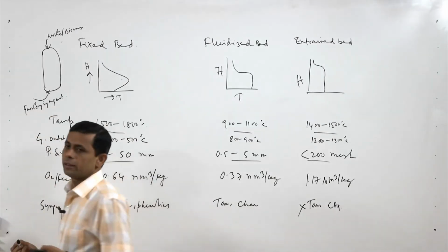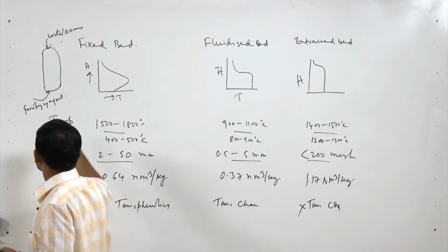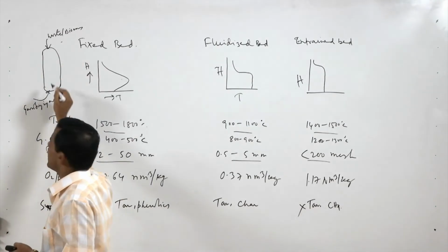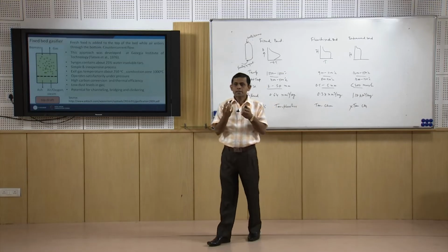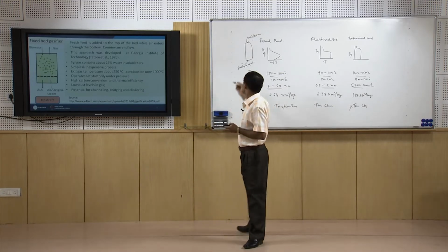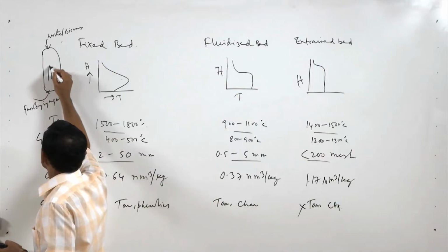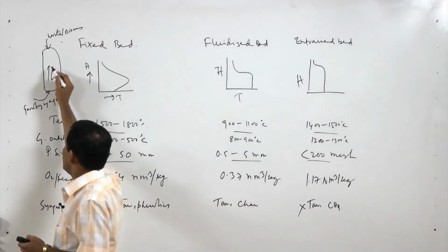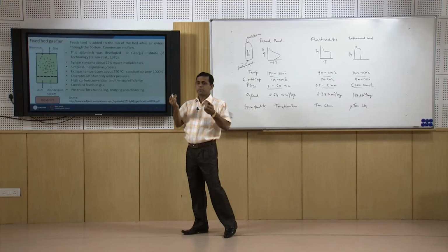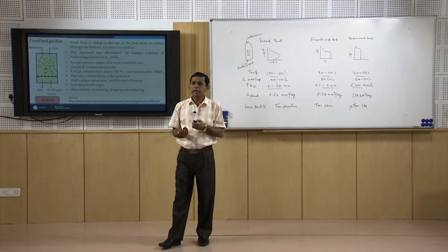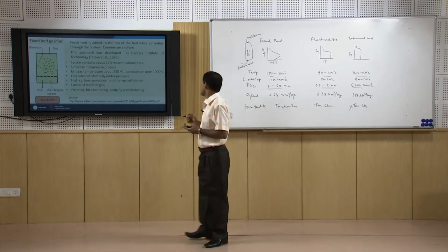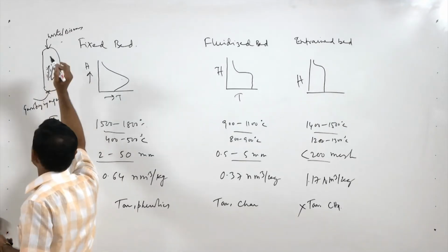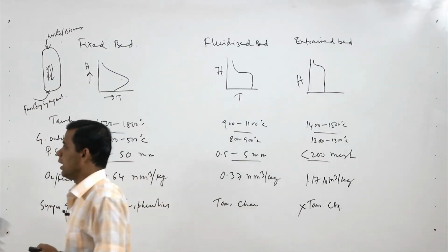This can be oxygen or steam. So, the biomass and waste and the gasifying agent get less time for contact because there is a counter current flow, and when the material is coming down, the bigger size particles and the gasifying agent going up, there is a good chance of blocking and channeling. So, there will be a chance of channeling and bridging.